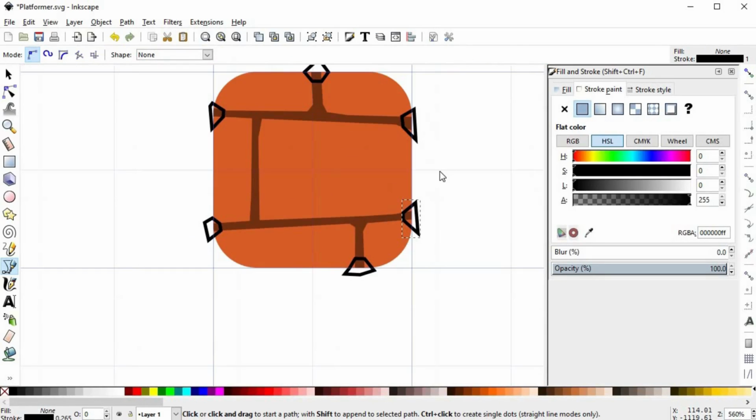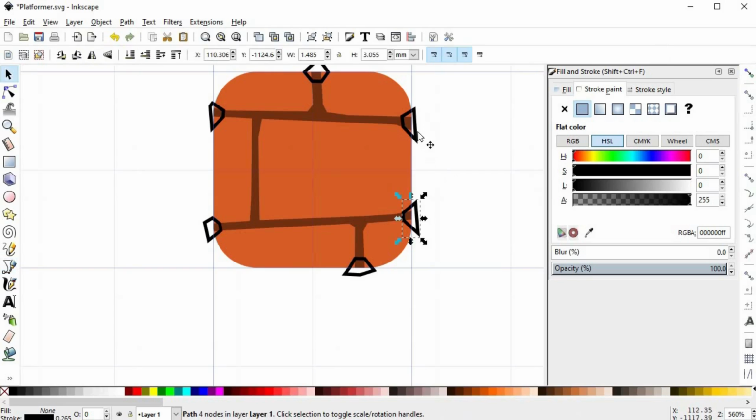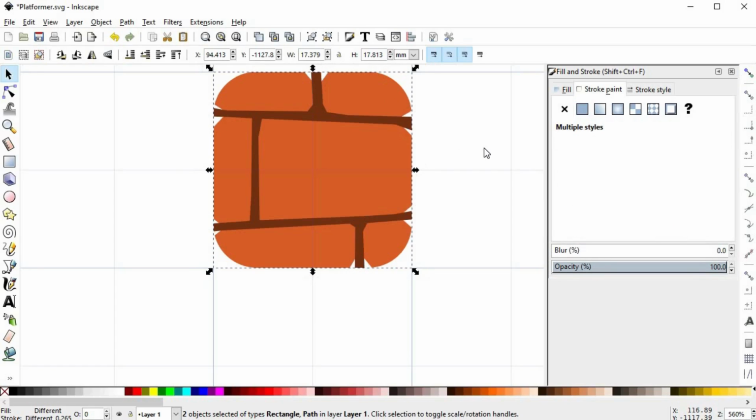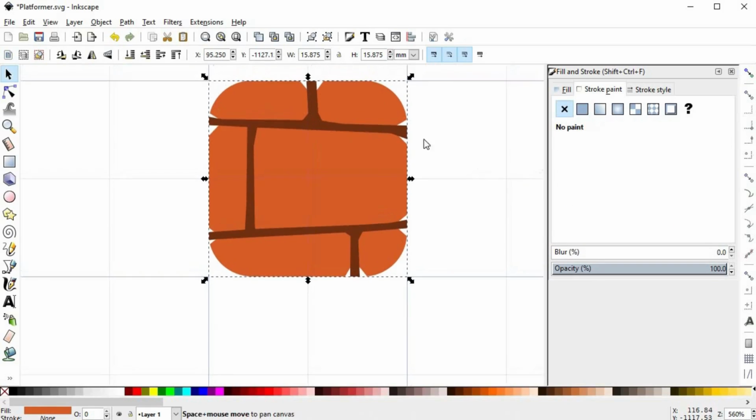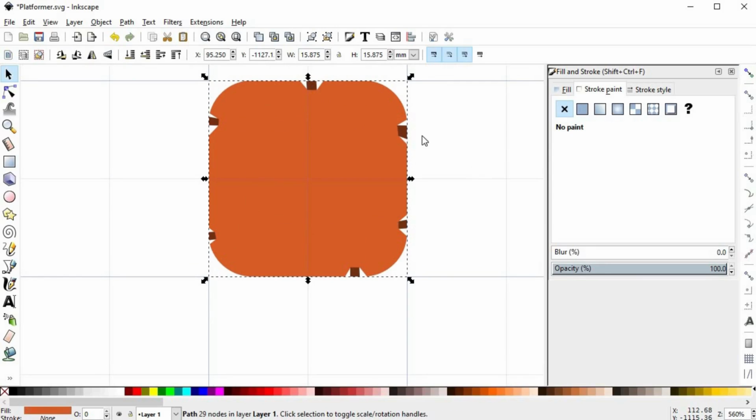Now, so you don't have to go one by one making 6 different operations, there is a nice little trick you can do. You can select all these shapes and join them into a single shape by using a union. And yes, unions work with shapes that are not intersecting. Now you have a single shape and you only have to do a single difference operation. And now the mortar joints need to be adjusted to this new block silhouette, so I'm sure you know what to do: perform an intersection with the block.